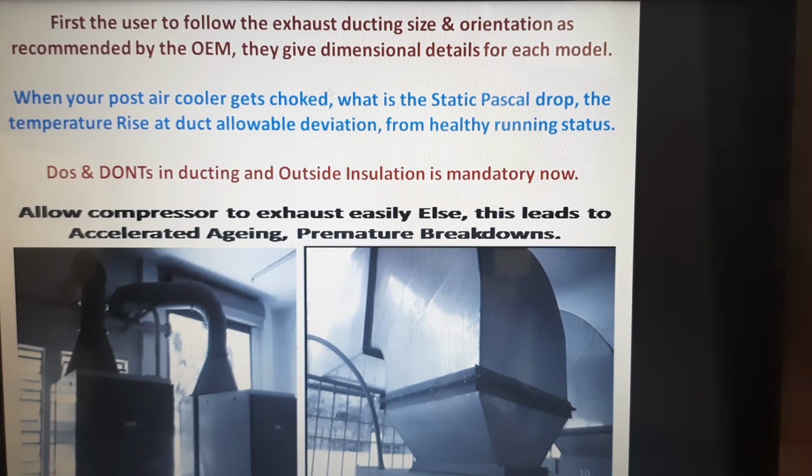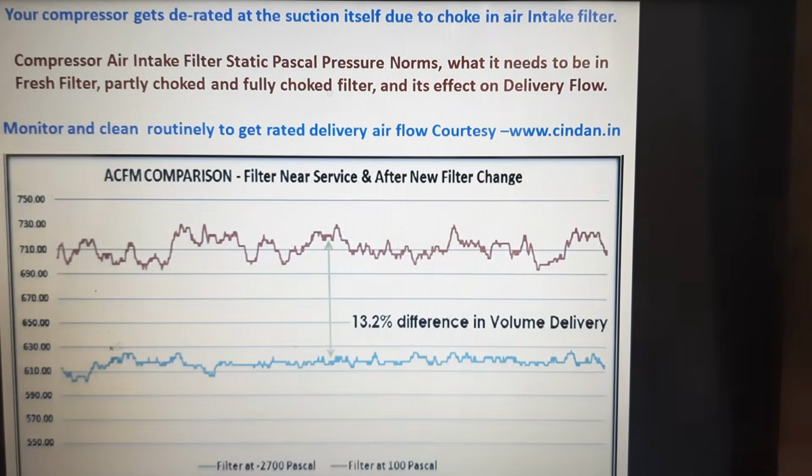So when the post-air cooler gets choked, automatically the static pressure drops as such. And definitely the temperature also goes up at the exhaust duct as such. So these are all the areas. Once we monitor the exhaust duct, we will definitely know whether the compressor is healthy. Let us say we are trying to maintain the health of the compressor on different aspects.